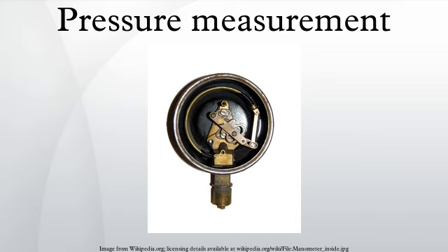Static and dynamic pressure. Static pressure is uniform in all directions, so pressure measurements are independent of direction in an immovable fluid. Flow, however, applies additional pressure on surfaces perpendicular to the flow direction, while having little impact on surfaces parallel to the flow direction. This directional component of pressure in a moving fluid is called dynamic pressure. An instrument facing the flow direction measures the sum of the static and dynamic pressures. This measurement is called the total pressure or stagnation pressure.